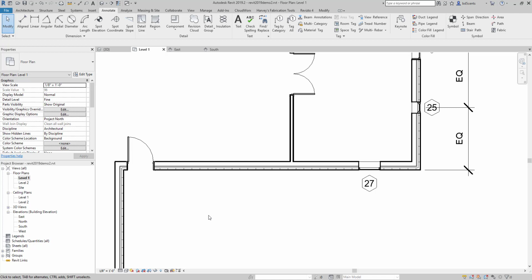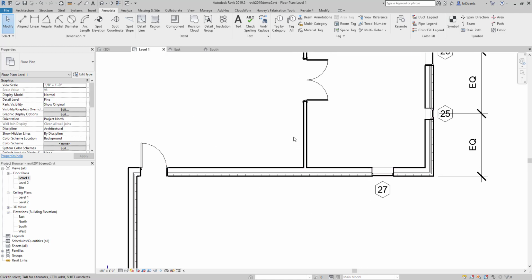Do you see the tag number on the elevation view for the window that we just created? When we went back to level 1, we tagged the same window and we noticed that the same tag is the same number. So again, all the information that you're putting into Revit is in a database. It is all being stored for use later in our schedules and other views, etc. So now we're going to move into plan regions and clerestory windows.